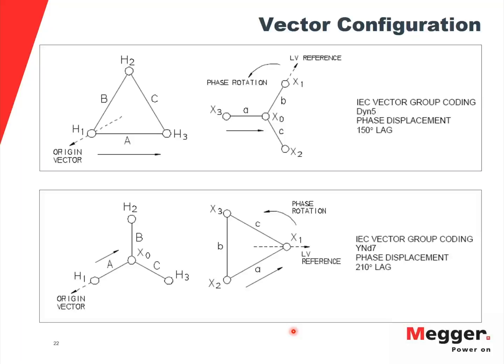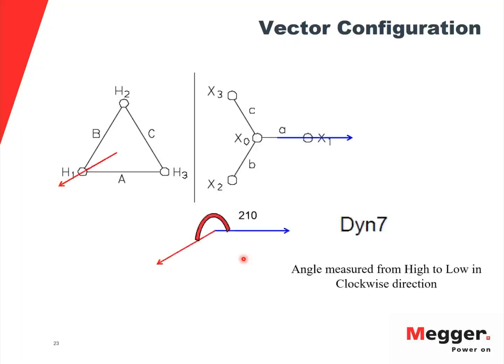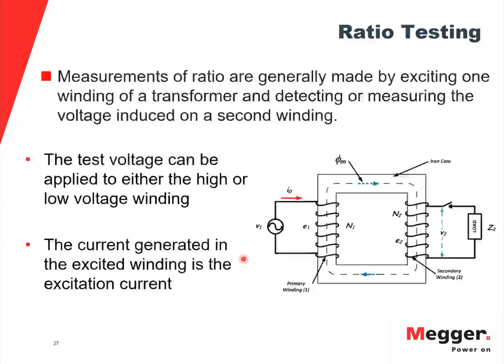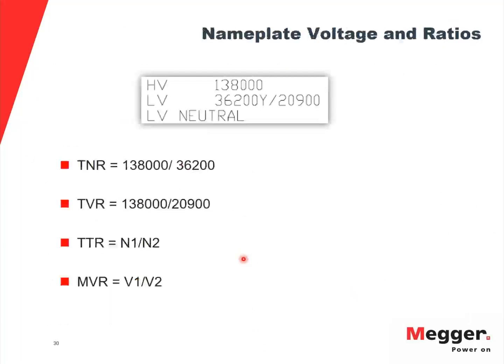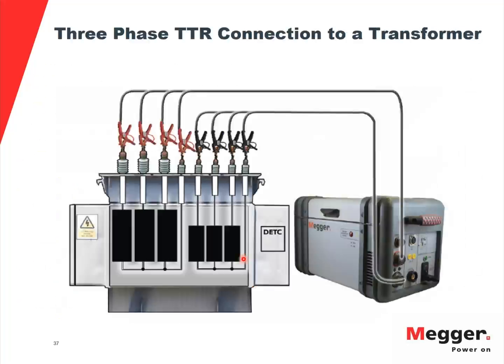So if you demagnetize your transformer, of course, you will minimize to a very low number this remnant magnetization in the core. And one of the things that is critical as well is not just for the energization of the transformer, but also for any additional testing that you may carry out on the transformer. If you did a winding resistance test, and after that you do some AC testing like ratio, excitation current, your leakage reactance, whatever the AC test will be next, especially for excitation current, you will see an influence of the remnant magnetization of the core on the results.